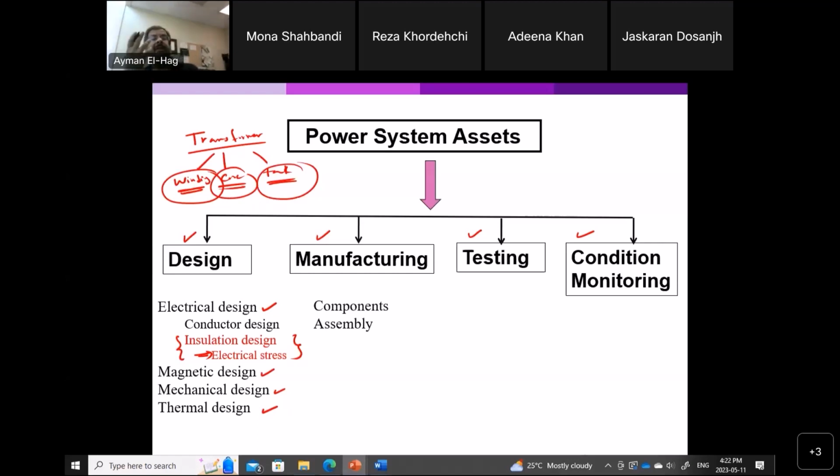You have to understand and know that oil and water shouldn't come close to each other. So if, for example, your factory is at a high humidity level, you have to make sure that you are degassing, or make sure that there is no moisture mixed with the transformer oil.